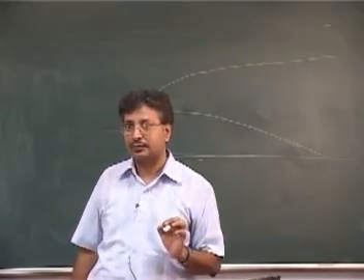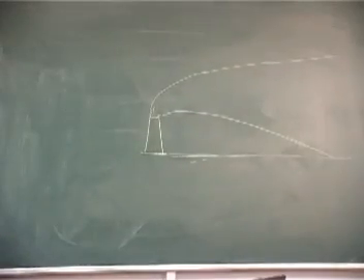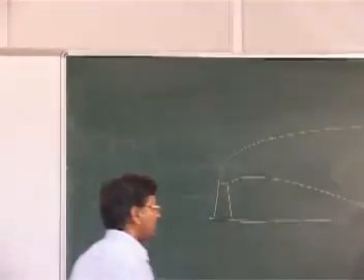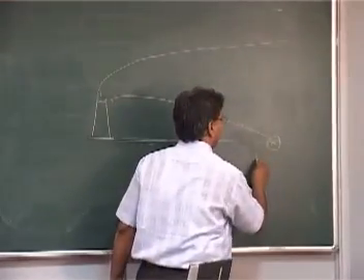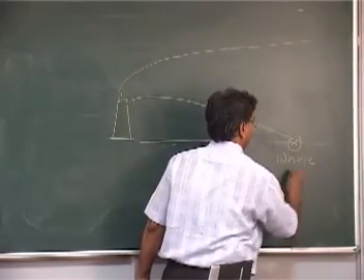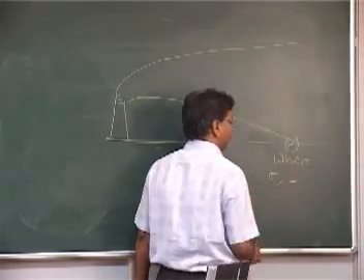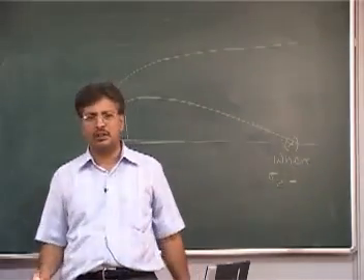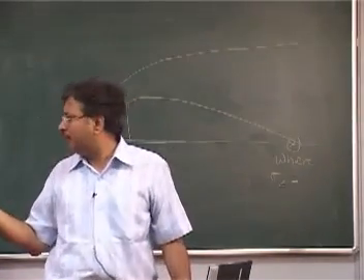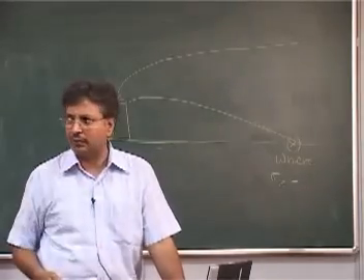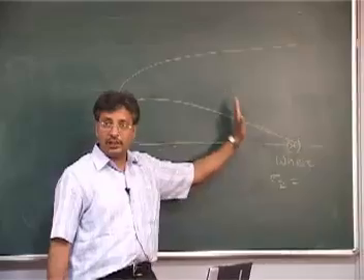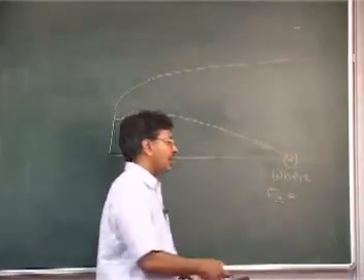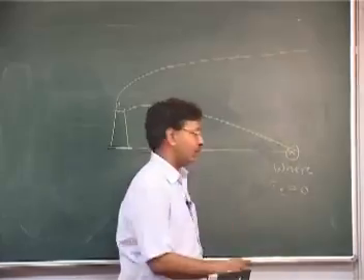Maximum impact of an elevated source. So I am just telling you that this situation may be somewhere here, where sigma z has become equal to 1 by square root 2, which is 1 by 1.41, so 0.7 something. So you see here that where sigma z, which is constantly increasing with respect to x, is nearly equal to 0.7 times h, I will write that number.